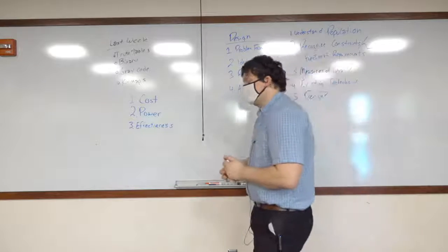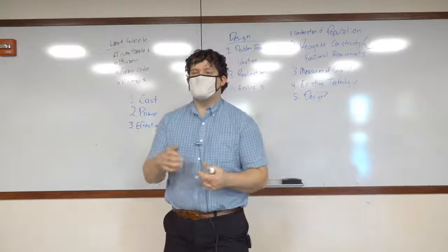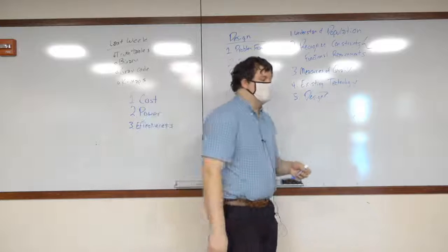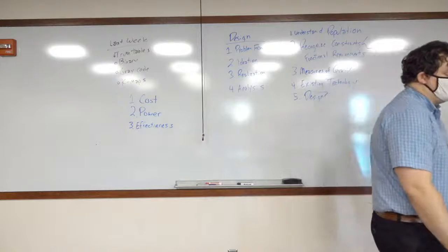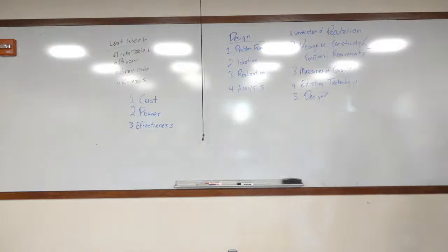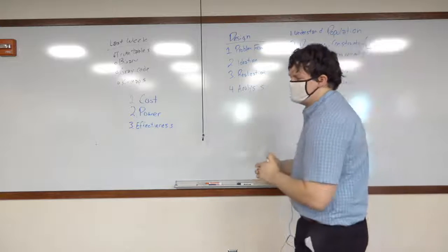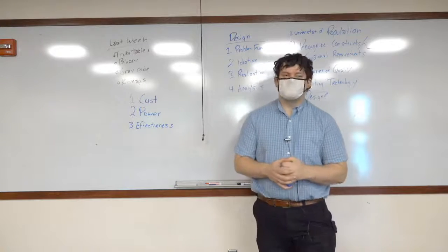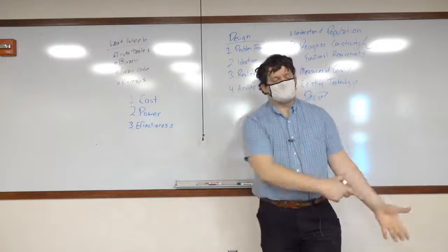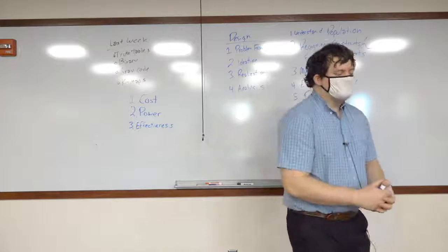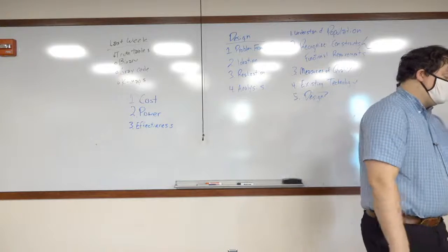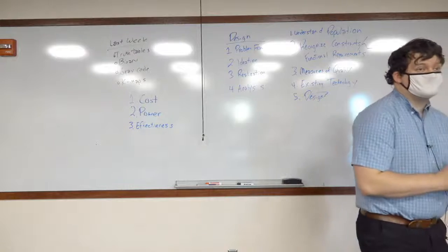High power systems tend to fail in fire. Low power systems may tend to fail by broken connections, simple, easily fixed. You may have a cracked resistor or a cracked IC. In that case, just replacing a component is fairly easy. But if you experience a fire, it may burn up your entire board. Maybe you have to replace the whole system. And that can be expensive, especially if you purchase that component from a company that no longer exists.